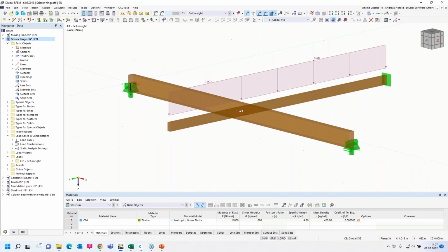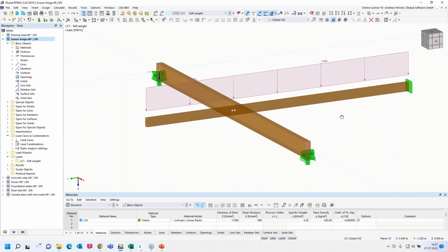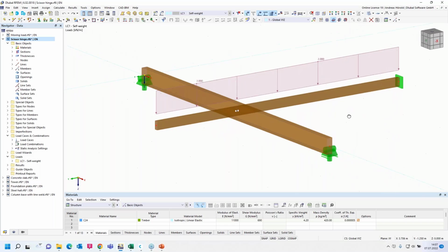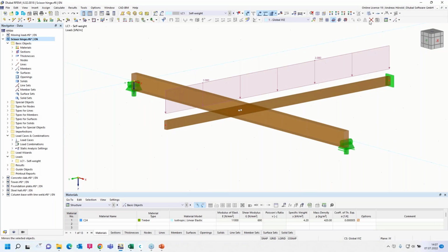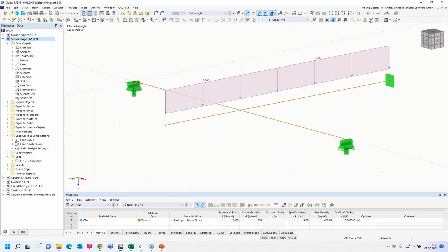Yeah, a scissor hinge can be used to model the crossing of continuous member. Yeah, for example, here, 4 members are connected to one node, and the members, these members here, transfer moments in their continuous direction, but not to the main member pair here. Yeah, and only axial and shear forces are transferred in this node. Okay, let's turn back to the wireframe model.